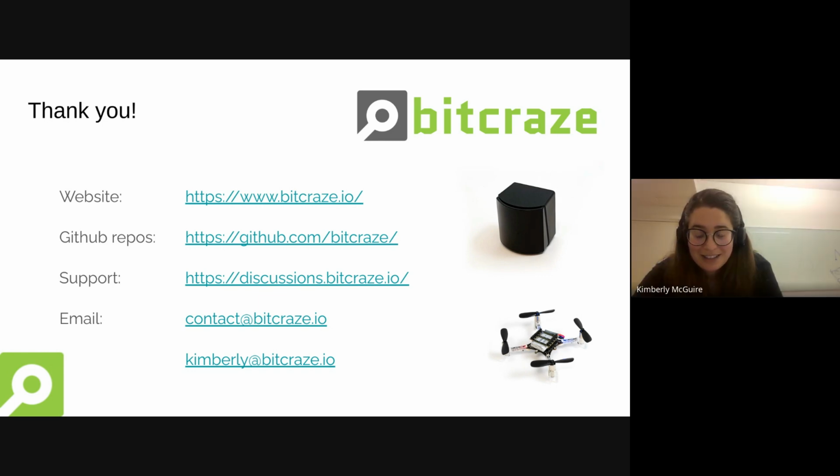No, not really. That happens very rarely. If there is any drift, and you don't have any yaw estimation, it would probably be the yaw at one point. But it really has to fly for a long time, and 7 minutes is usually not enough. But since we do yaw estimation, that hardly ever happens. I think drift will only happen if it loses connection with both base stations. It always has to see at least one in order to do position estimation.